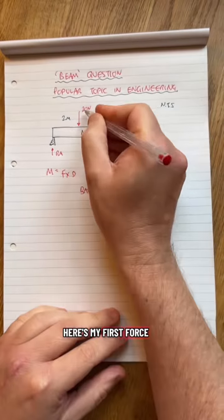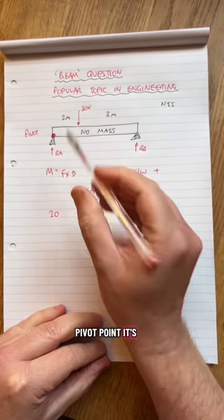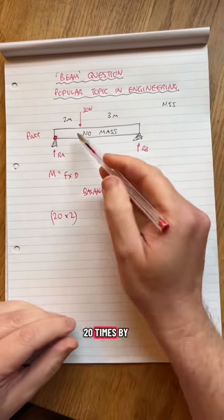Force times distance. Here's my first force. Here's 20. Here's my pivot point. I'm going to go from there. How far is 20 from my pivot point? It's 2 meters. That force is trying to make this beam do this. It can't because that thing's in the way. 20 times by 2. There's my one force.